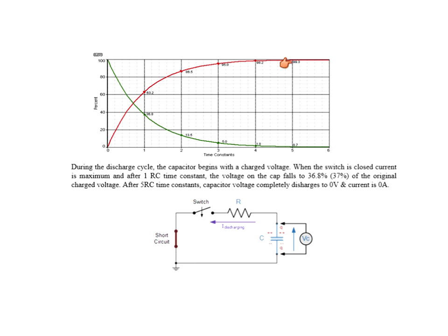During the fifth time constant, there's very, very little change or any current moving. So when you charge, after 5 time constants, the current goes to 0, but the cap receives full voltage. When you discharge, you get a lot of current at first, just like charging, but after 5 time constants, it goes from the full voltage to 0 voltage.